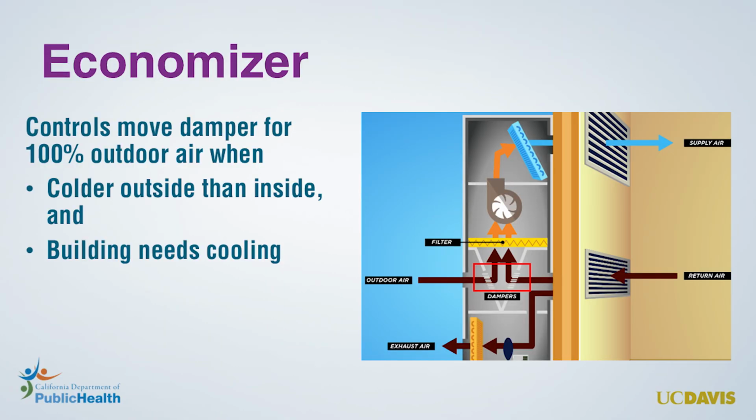In certain ventilation systems, the rate of outdoor air intake may vary. Systems equipped with an economizer feature an outdoor air damper assembly controlled by a motor to regulate the ventilation rate. Typically, the motor maintains the damper in a static position to meet the minimum ventilation requirement. However, when the building needs cooling and it's cool enough outside, the outdoor air damper opens to 100%. This process enables free cooling, reducing energy consumption.